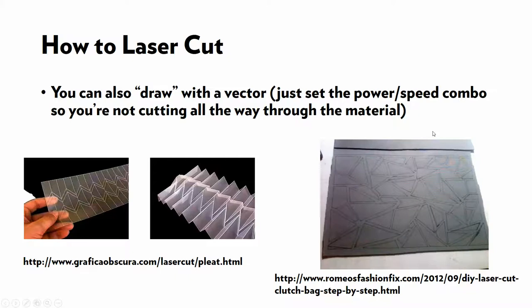You could also do the same thing to mark on metal for bending in sheet metal, or mark on wood for then cutting with a bandsaw. If, for example, you had material that might be too thick to cut on the laser. You could also just laser cut a pattern and then glue that to the piece of material you're going to cut.